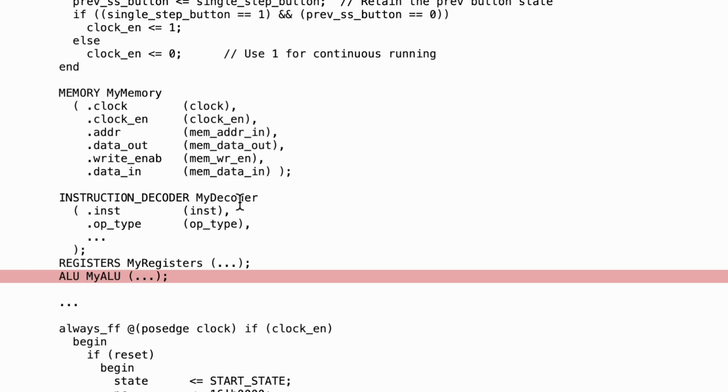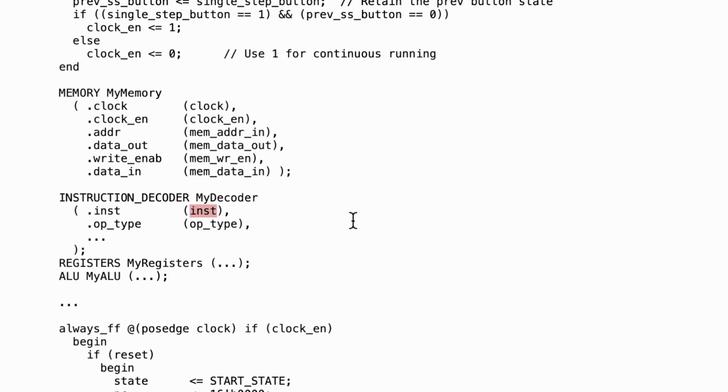The instruction decoder will take as input the current instruction that's being executed, and it takes it apart and figures out a number of things and isolates various fields in the instruction. But the thing that we're concerned about today is that it will determine what type of instruction it is. So we have an enumeration with various types for the different instructions. We've got ALU, move immediate, move, load, store, and so on. So for example, we've got one type code for all of the ALU instructions.